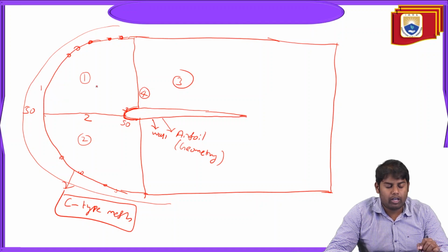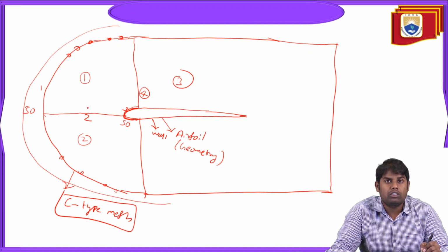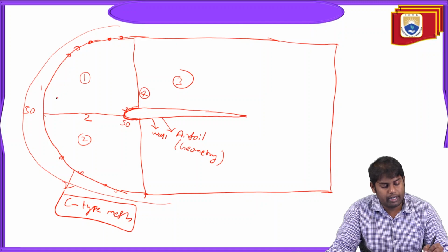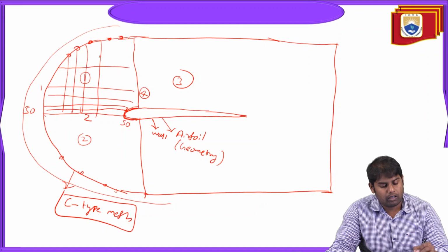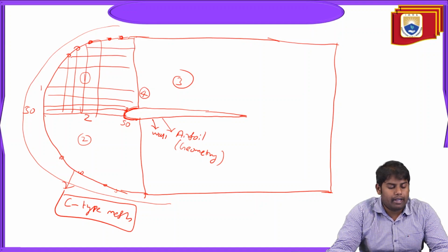If we want a closed setup or closed boundary, what we need to do is divide into subdomains. Initially we don't have this line. When we draw this line, it divides the overall domain into two subdomains, subdomain 1 and 2. Now by creating the subdomains, what is the advantage? We have created 4 walls or 4 surfaces or 4 boundaries, this 1, 2, 3, 4. These 4 boundaries or entities form a closed setup. This closed setup will generate a structured mesh. It will generate grid lines like this. As a separate entity, it will generate grid lines like this.